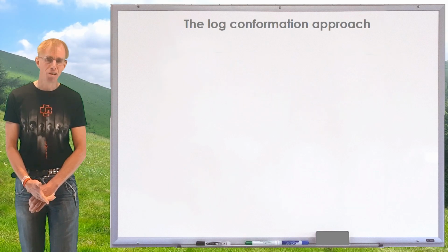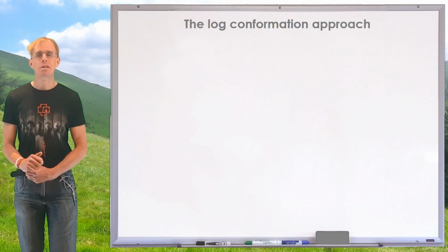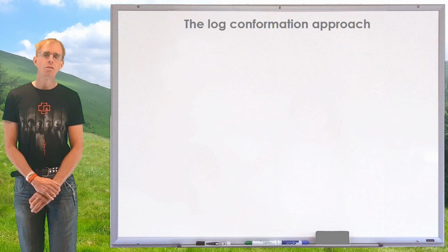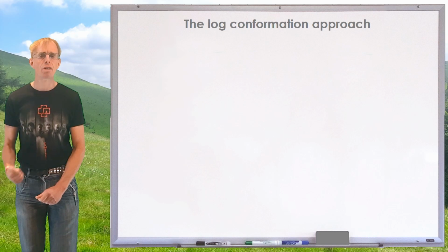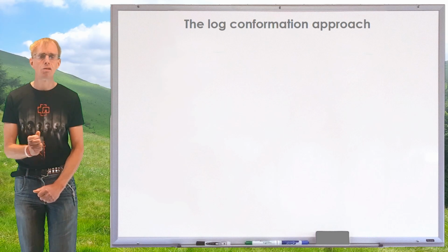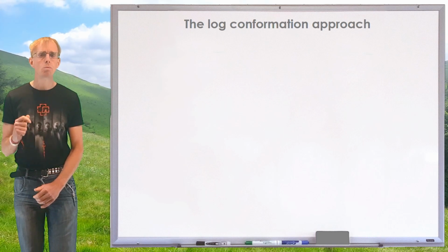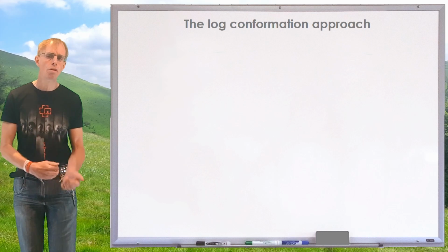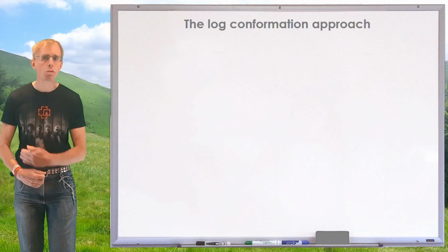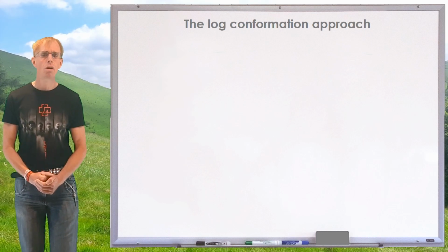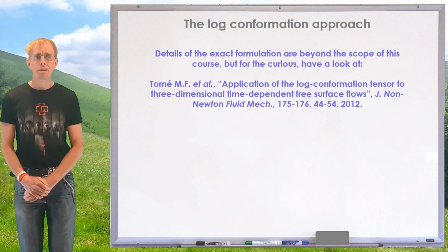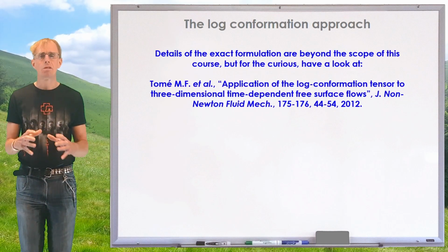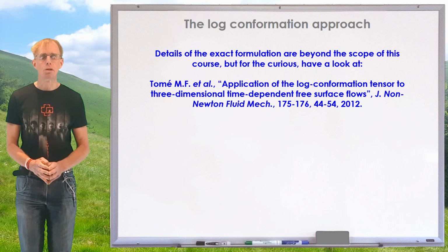However, solutions have emerged. About 15 years ago, it was realised that, well, why don't we just do this a different way? If we've got equations diverging to very large values over a very small perturbation, why don't we look at the equations written in logarithmic form? Because then we're not going to get that divergence to large values, which means that we can keep our numerical schemes more stable. And that's the core concept that underlies the log-conformation approach.